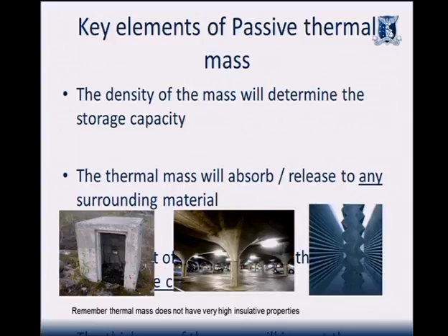Here's some examples of thermal mass. So something like that is trying to average the conditions. Obviously the openings are a bigger effect. That car park underneath the south lawn is very, very stable in temperature, very high surface area of thermal mass. And this example here, this is the labyrinth at Fed Square.